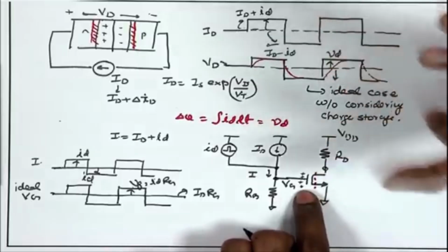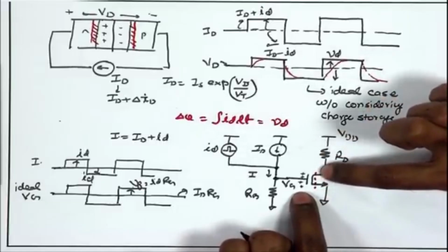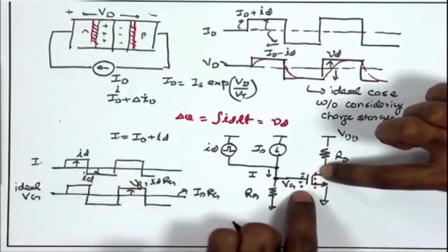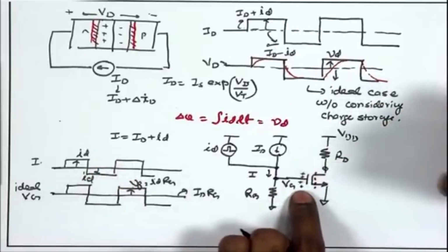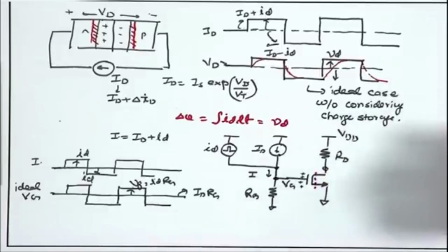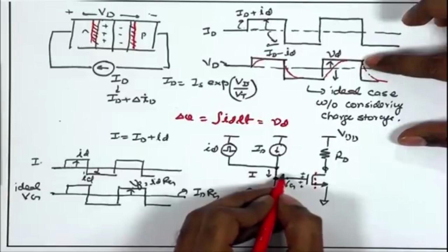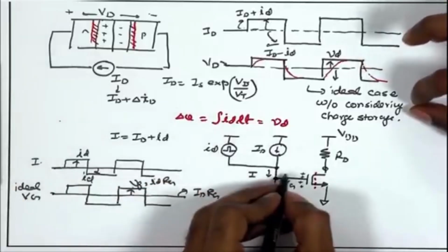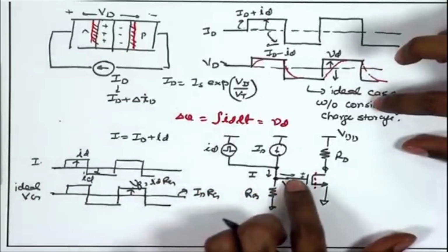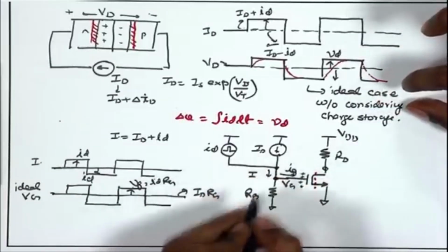The electrostatics will force the electrons to accumulate and balance the additional positive charge that you are trying to produce. For the negative cycle of id, you are trying to reduce the positive charge here, that is, you are trying to reduce the voltage, which means it is going to reduce the negative charge over here. So, once again this charge storage will not change instantaneously; you need to integrate the current for a finite duration, whatever is the small current going to the MOSFET, which I call IG.